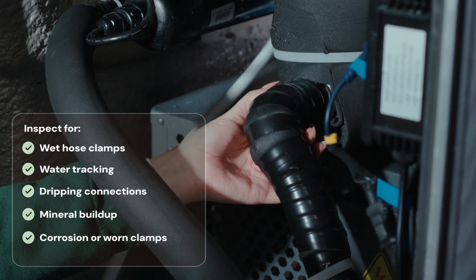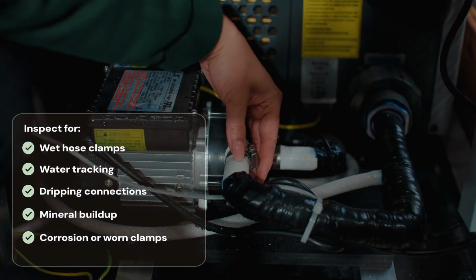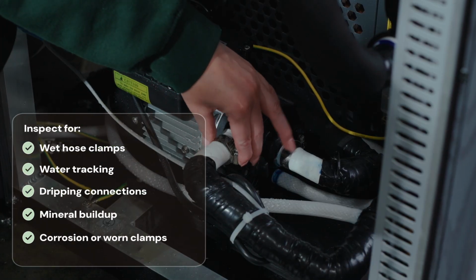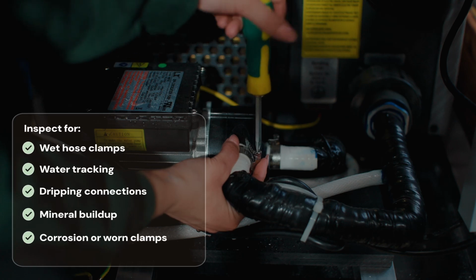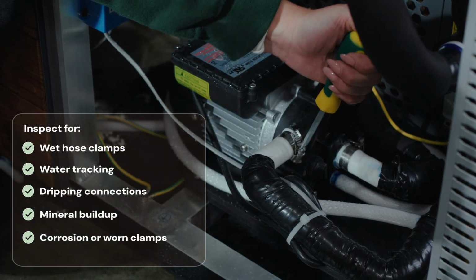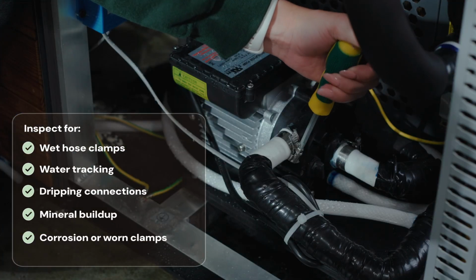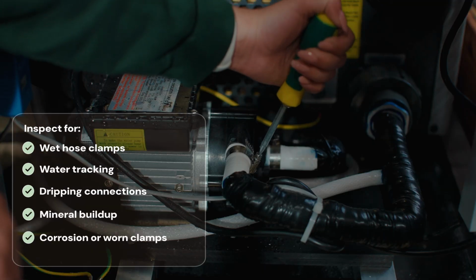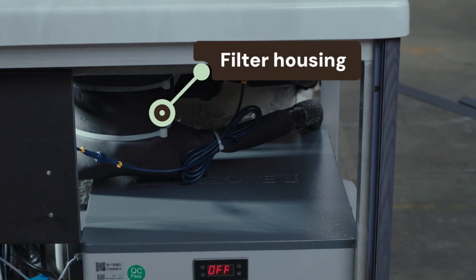Carefully inspect all plumbing connections for moisture, loose clamps, corrosion, or signs of water tracking. Minor leaks are often resolved by tightening or repositioning the hose clamp. If the hose is improperly seated, disconnecting and reseating the connection may help create a better seal. If hose clamps appear heavily corroded, damaged, or worn, replacing the clamp may help restore a more reliable seal and prevent future leaks. Next, inspect the filter housing assembly.